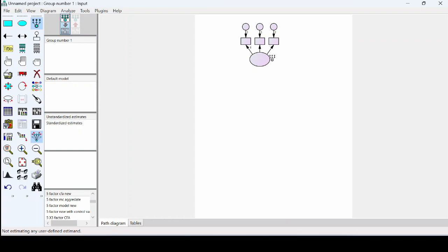All right. If you want one more, you have the option to copy this as well. To copy all this, this is the function duplicate objects. If you click this one, and then select this one, be careful with it: it means that all of this will be copied. If it's not selected, then only whatever you are copying will be copied. Now here you see it's not selected.